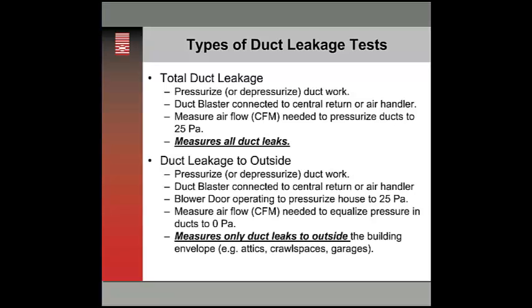You're connecting your Duct Blaster fan to a central return or an air handler, and you're going to pressurize it. You're going to seal the system and pressurize it to 25 pascals. The total duct leakage will measure all of the leaks. It's the whole nine yards. What is the total, both inside the building and outside the building? Duct leakage to the outside, again, can be done either by pressurization or depressurization. Same setup, you're going to connect the system, but you're going to need a blower door. And the number that you end up with is only the leakage to the outside.